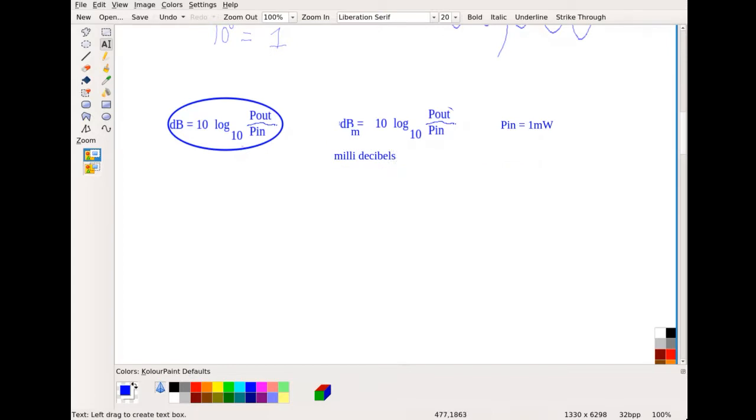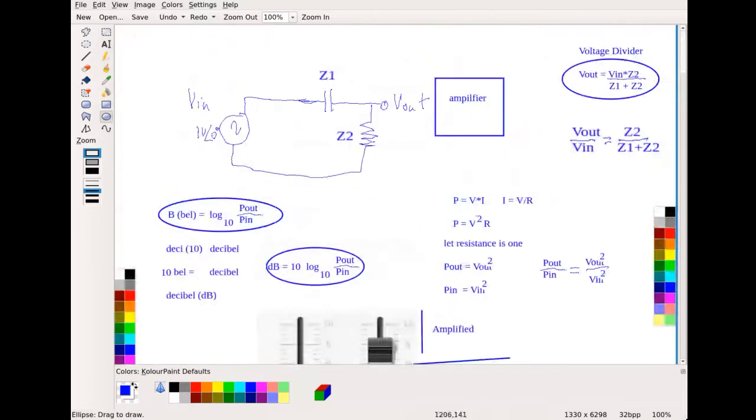All right, but the other thing is, as I talked about up above, decibels is really all about the power. However, we can't measure power as easily as we can measure the voltage, right? So if we come back up here to this equation, we get that the power is this voltage squared divided by the resistance.